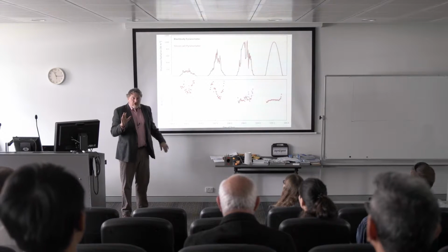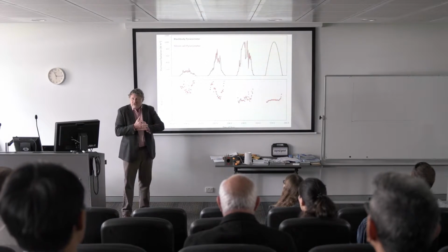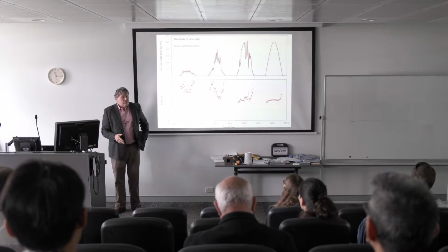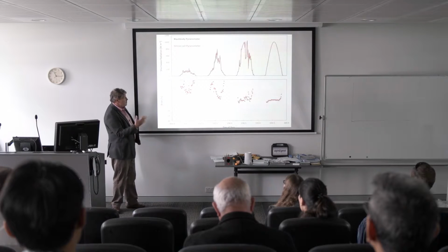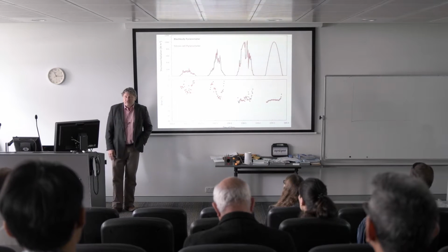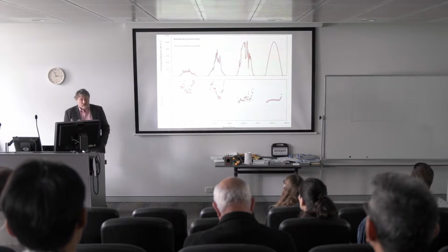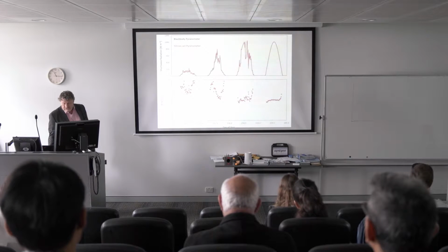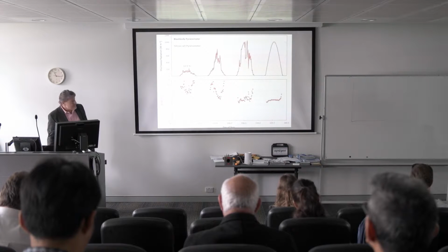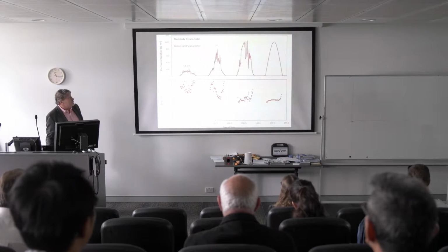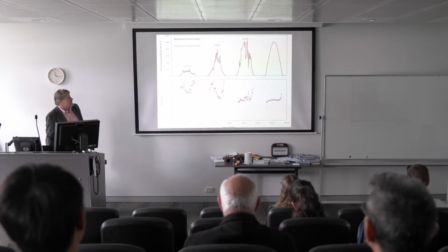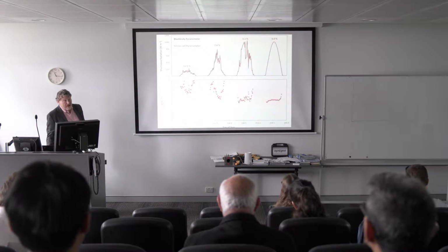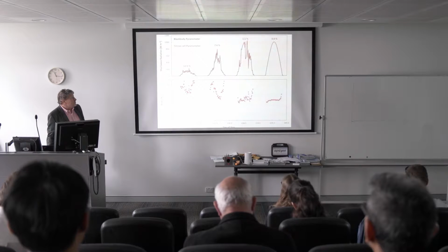You can, of course, correct for this if you know the effect and you know the fraction of clouds, but rarely do people do this. They just assume the silicon cell is correct at all times. So there's a bottom line, there's a humidity effect on this measurement. Here's the magnitude of the effect here. And again, they're accurate in full sun because they're calibrated to full sun.